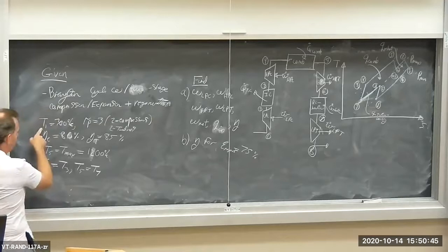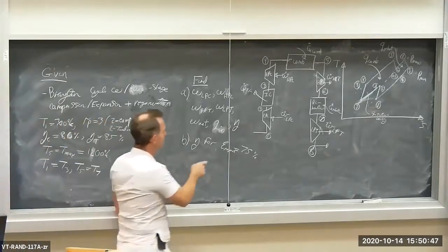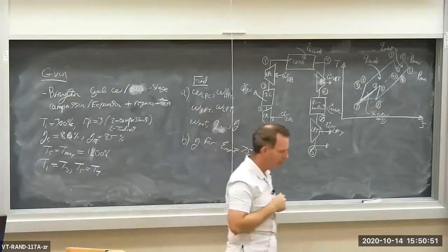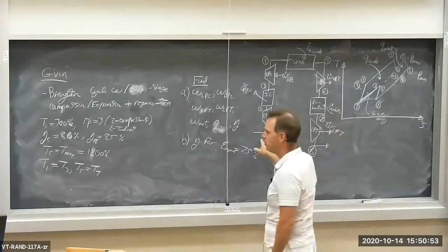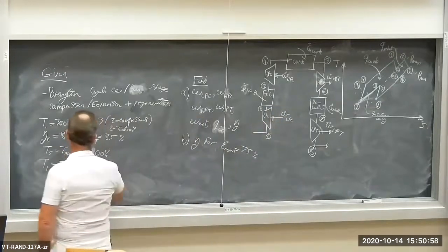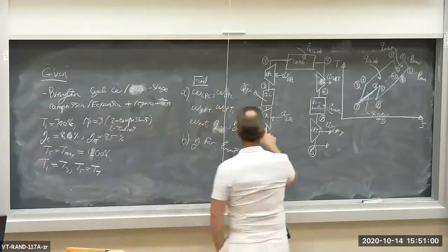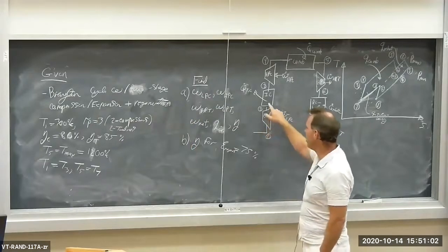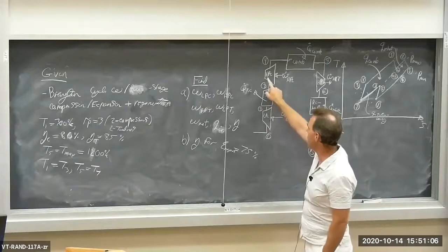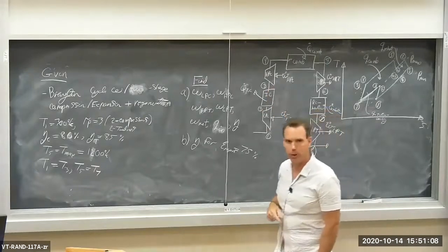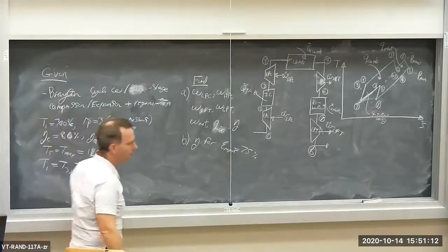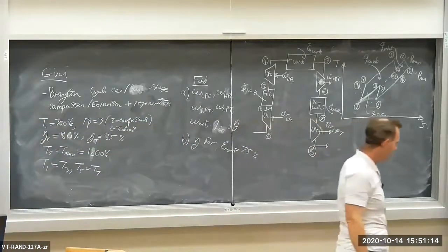We have the low pressure compressor, LPC, inlet temperature of 300 degrees Kelvin. And then once the compression occurs, we go into an intercooler and we reject some heat. And then we go into a HPC, high pressure compressor, that's the second compressor, and we pressurize it all the way up to the maximum pressure.